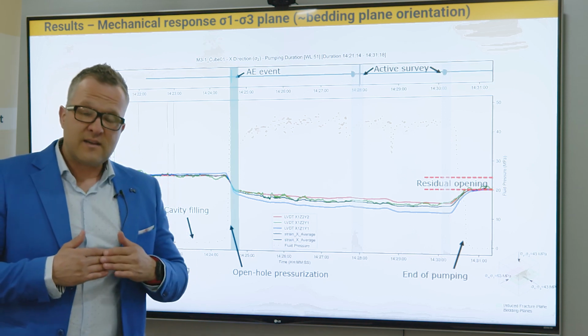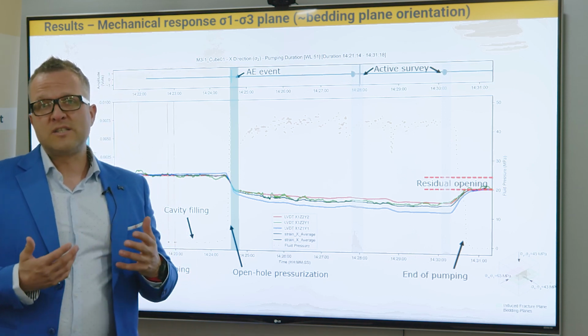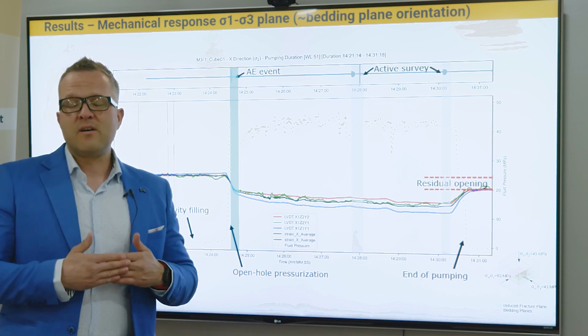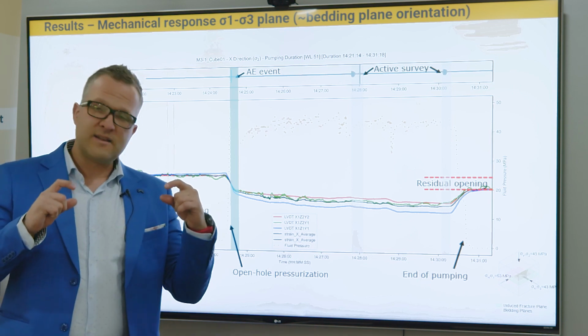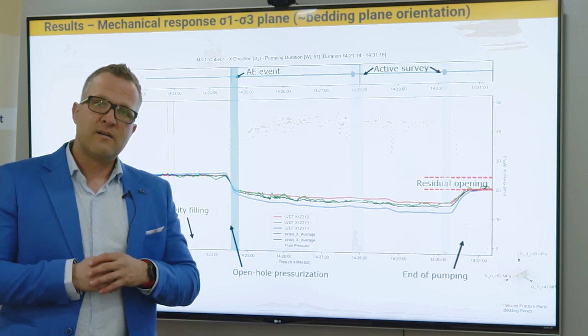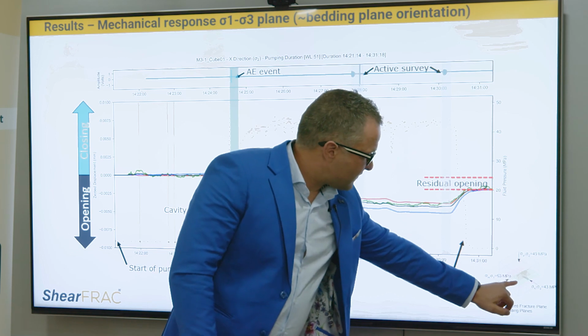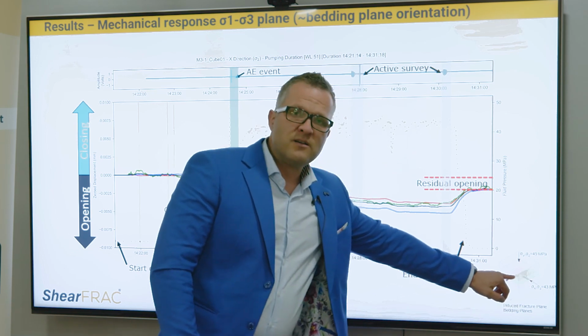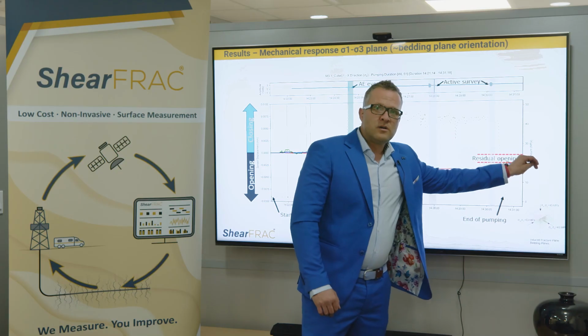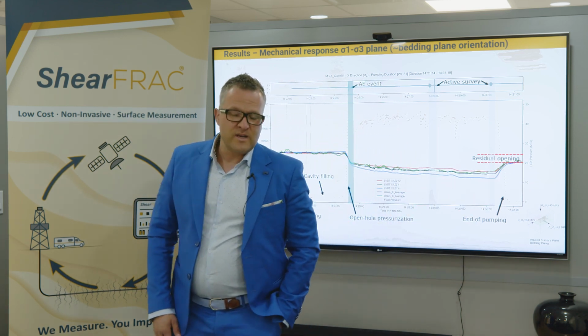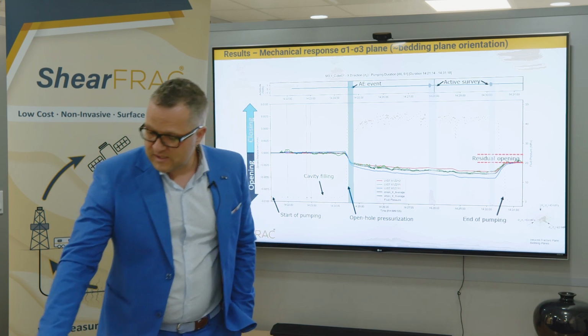They have lower tensile strength, and we see this in all shales. Even if you go to a quarry which mines flagstone, they cleave along the bedding plane parting to make nice, thin, laminated shale flagstones for your garden. So you can see here, the induced fracture planes actually went parallel to sigma 2, which should be a real head scratcher because we know the forces applied within this machine.